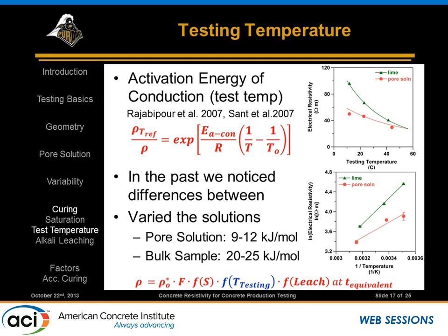And the reason for this is because what's being captured in this particular test is not only the effect of temperature, but it's the effect of leaching, like Mike mentioned earlier. So even at very short times placing these samples into a bucket of water, there can be substantial leaching taking place inside of these samples.